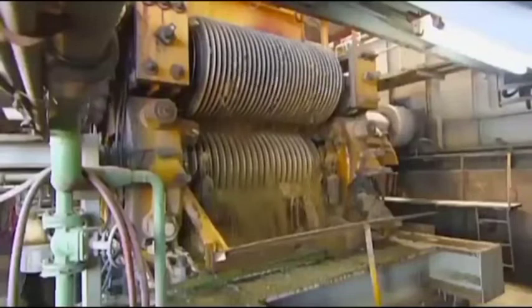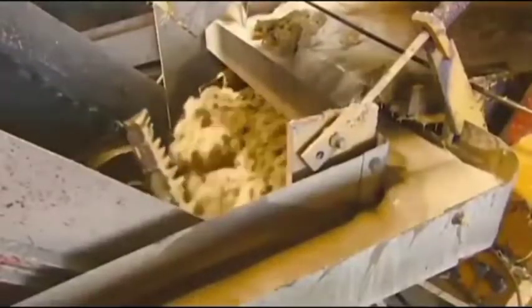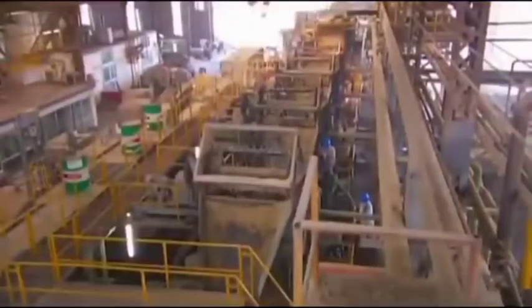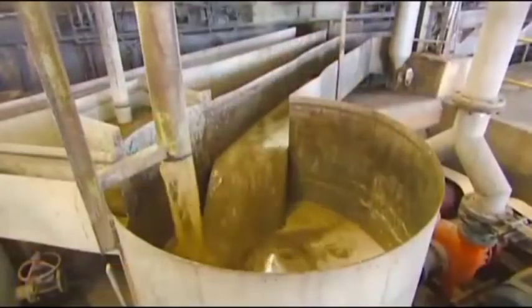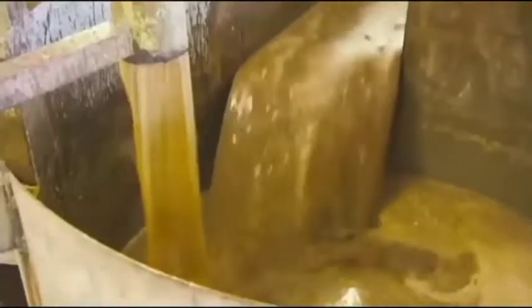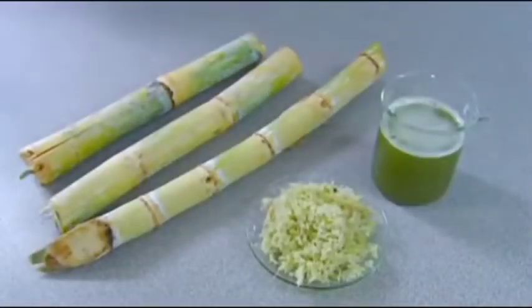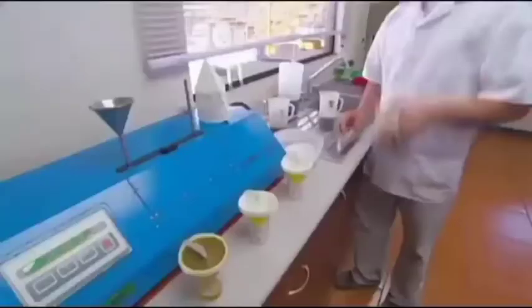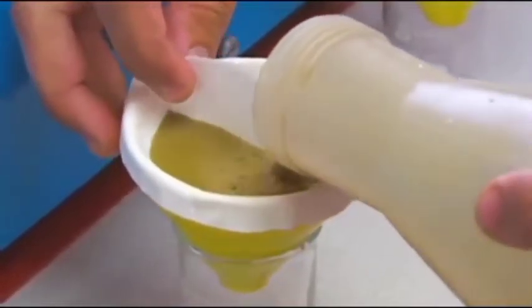Feeder. 1. Feeding roll. The feeding roll is a feed roller that is under the bagasse layer, so it is also called an underfeed roller. The diameter of this feeding roll is about 1/3 to 2/3 of the diameter of the mill roller. Circumference speed or RPM is approximately 1.3 until 1.5 times the milling roller circumferential speed. This feeding roll is driven by the advanced roller via sprocket and chain transmission. Feedability can be improved by providing grooves on the rollers, 8, 10 until 13 mm pitch.